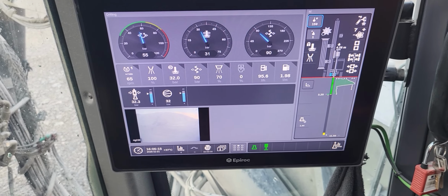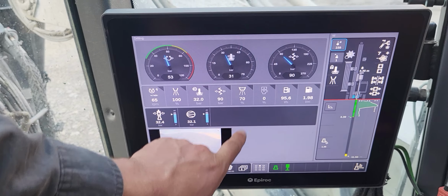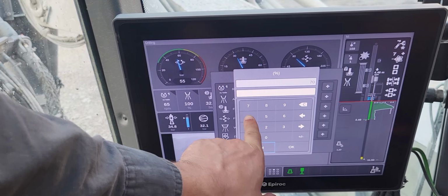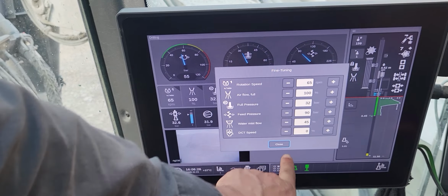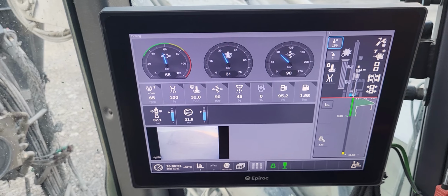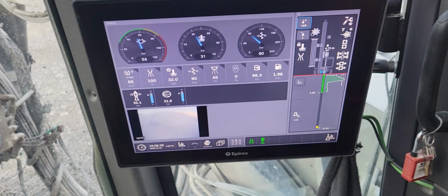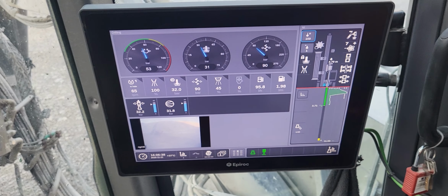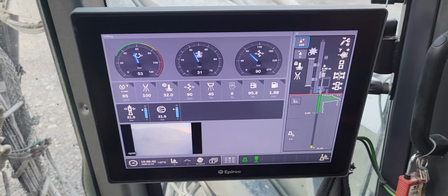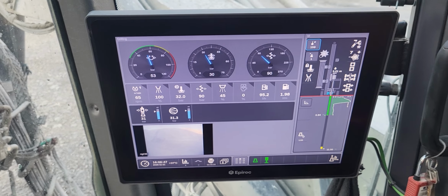Once we finish the collar, we can go down normally with the water, so we decrease the amount of water just for dust control and keeping the hole stable, since their client doesn't want to use the dust collector, or requested that the dust collector be disabled.